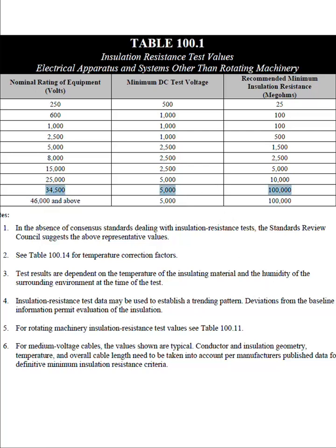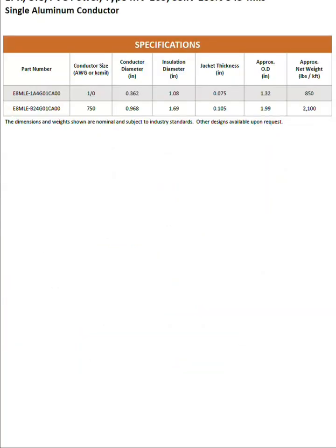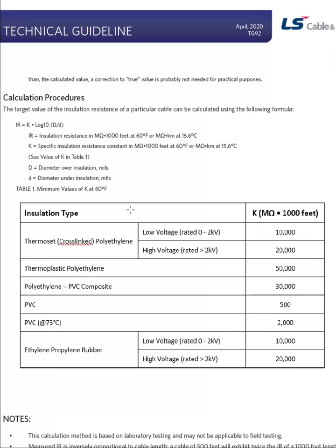Okay, so the NETA table is not gold, it's just a guideline. What is gold, what NETA is going to tell you to follow, is the manufacturer specification, and that right here is how you follow it for medium voltage cable. So hopefully this helps.